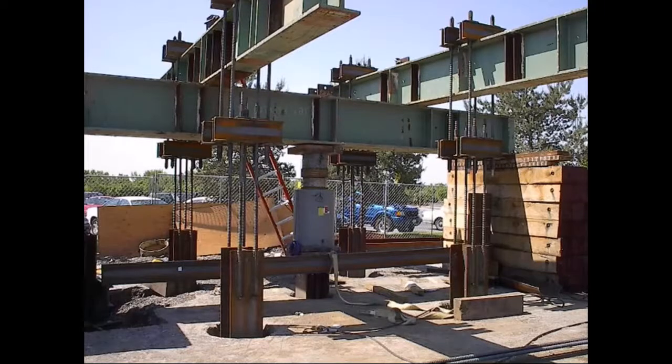And here's an actual setup. So you can see from this setup, there had to be 4 reaction piles installed for this project just to test this one pile. So you can see there's quite a lot that goes into that. And typically the contractors are required to set this up, and the inspectors or engineers will be out there to monitor the test and record the test results.